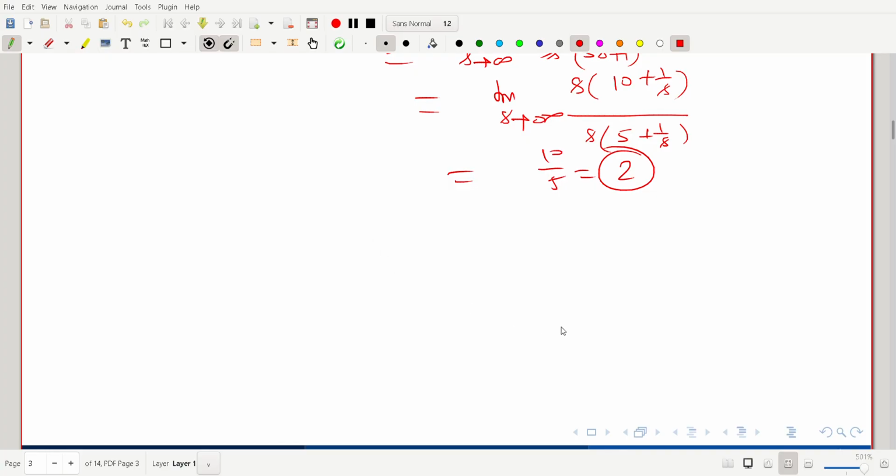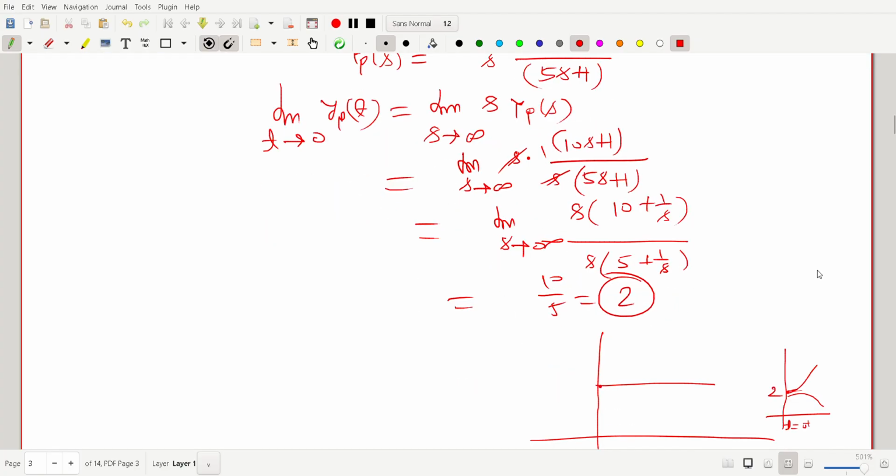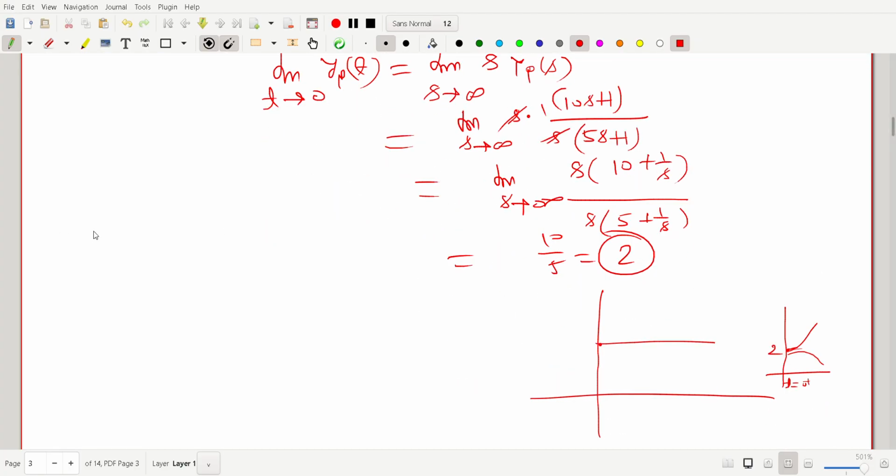So the output at the initial instant will be like that. If you apply a unit step input, our output will start just at t equals 0 plus with some value, 2. After that we don't know whether it goes up or comes down. For this we require the final value theorem. If you apply the final value theorem, with t tends to infinity, the answer would be 2.